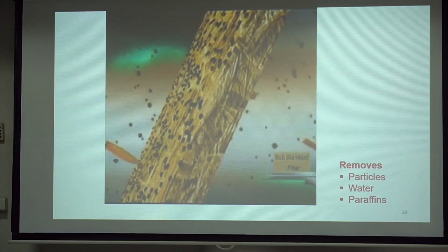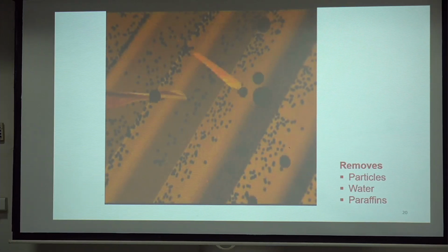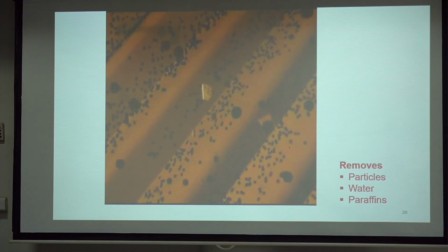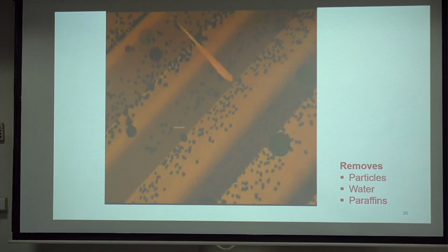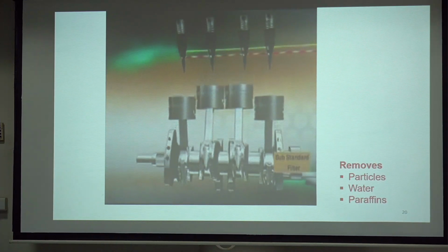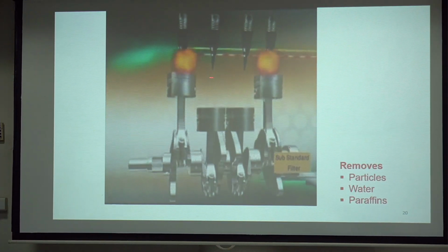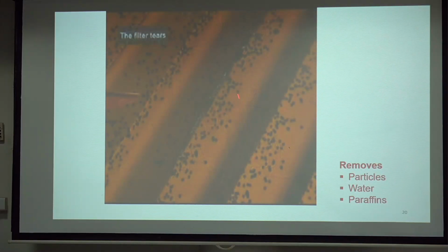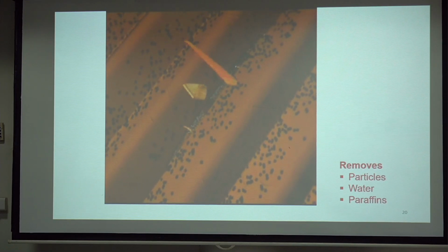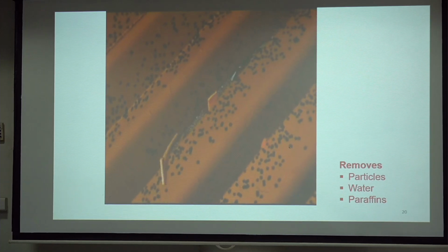They also have a much lower dirt absorption capacity and have to be changed more often because they clog up more quickly. Fuel is pumped against a high resistance. See, the injector nozzles are getting blocked. If the filter medium is blocked, obviously it will not perform properly, and dirt can enter the injection system almost completely unfiltered.